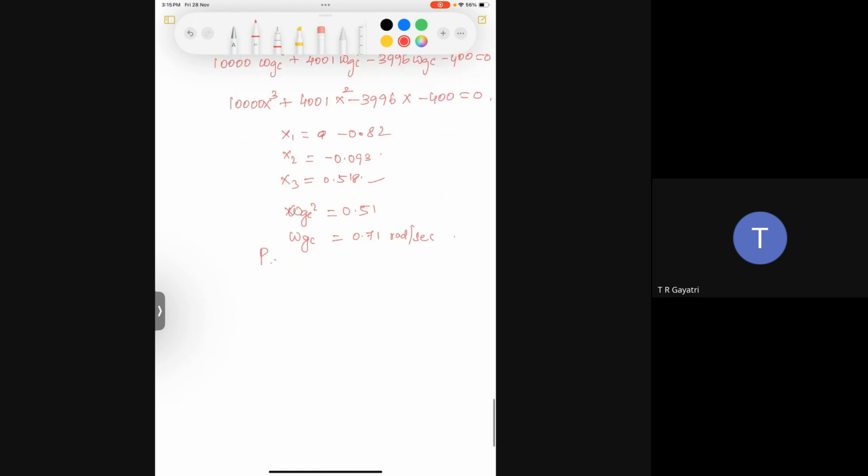So finding the new phase margin will be 180 plus the phase at omega equal to omega GC. This is to let you familiarize with all the equations and formulas. So this will give me 180 plus, for the open loop transfer function we already know, minus 90 minus tan inverse of omega GC by 2. This is for our 10 by s into s plus 2.